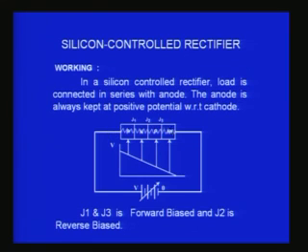So, if you look at this entire thing as a silicon block, then it has a very specific resistance, and if I connect the resistance, at this point the voltage will be the applied voltage, full voltage, and if I go along the resistor at different points, you would find the voltage will be slowly decreasing till it comes to 0, because there is a drop along the resistance. We know that from Ohm's law.